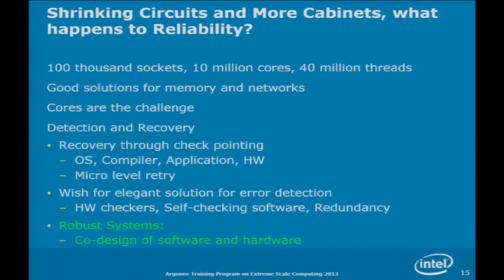One of the ideas that has been bandied about for a long time is modular redundancy, where you do modulo 3 arithmetic, and you can use that to recover. You do the modulo 3 arithmetic in parallel with the operation. You know why that works? It works for the same reason as checking whether a number is divisible by 3: you see if the sum of the digits is divisible by 3. That's equivalent, and it's the same in binary. 4 is equal to 1 modulo 3, and you can use modular arithmetic. Think about that if you have time.